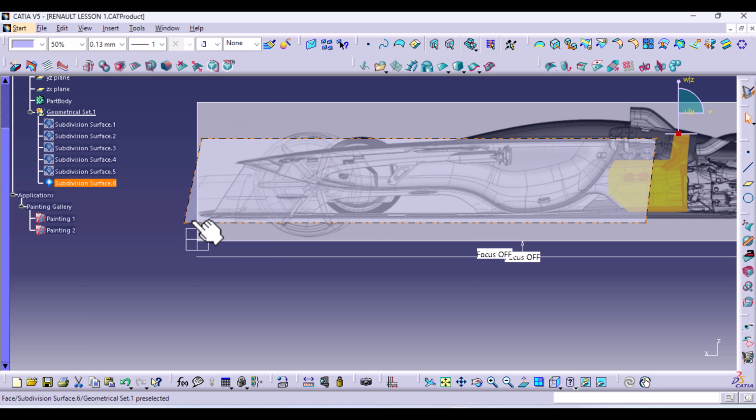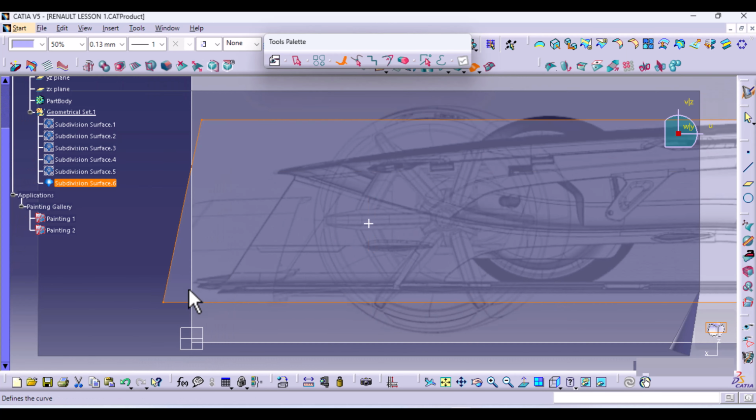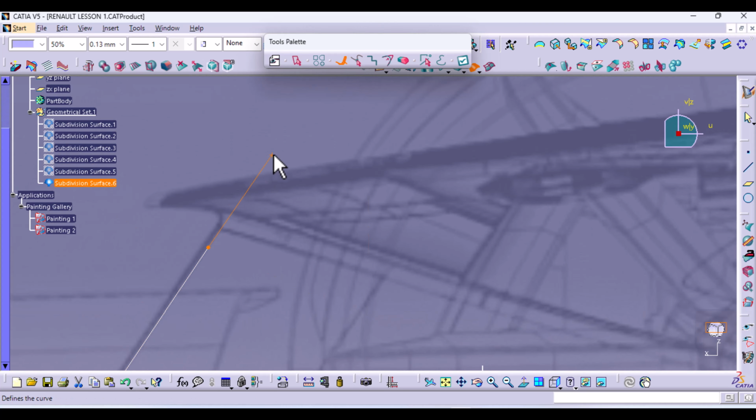Then we need some surfaces to cut it to the desired shape. So we have extrude. It's really simple. So you can cut it straight, and then when you change your surface to a thick surface, a thick solid, then you can apply an edge fillet here.